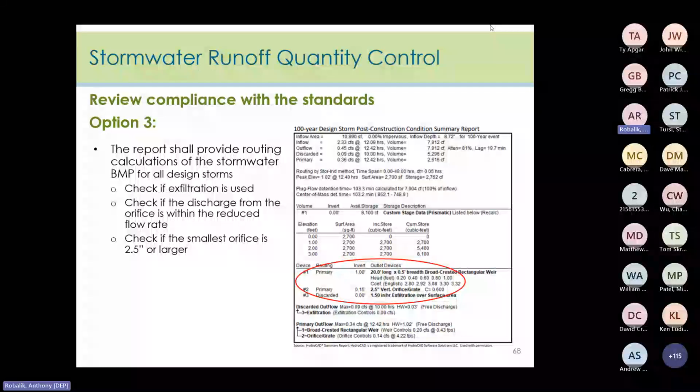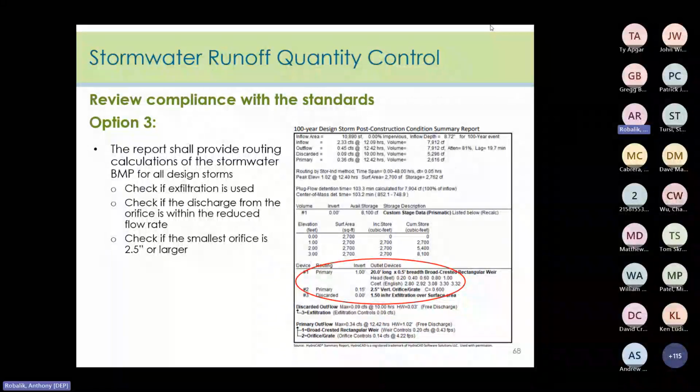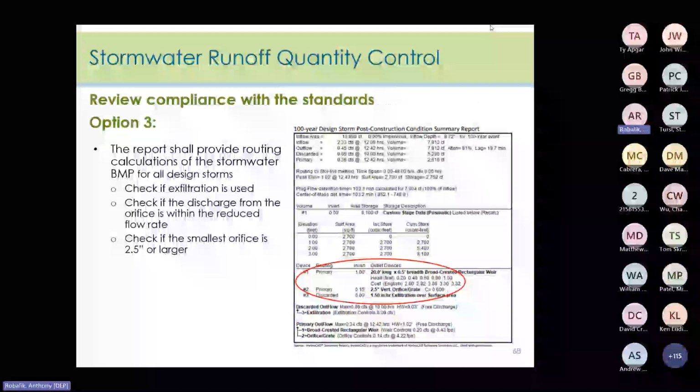So here's an example pond report. We'll take a look at this particular printout on the next slide. But on this type of printout, it's important to check if exfiltration was used in the routing and whether or not that is permissible, depending on the BMP used.